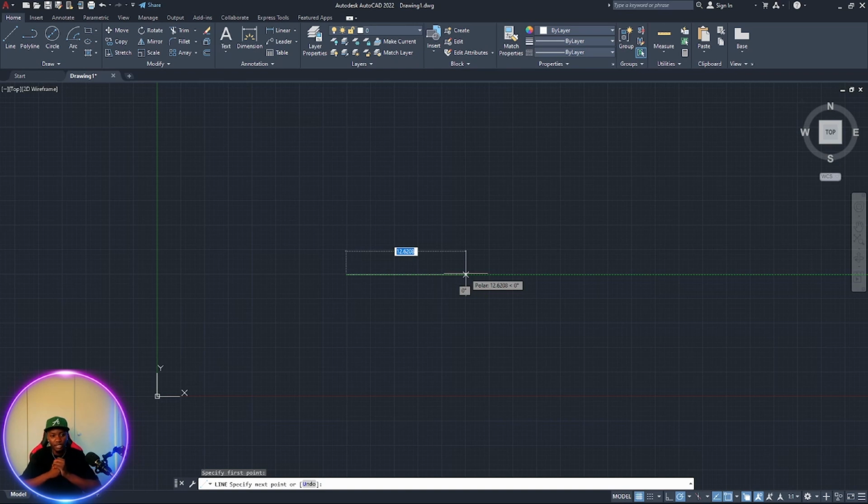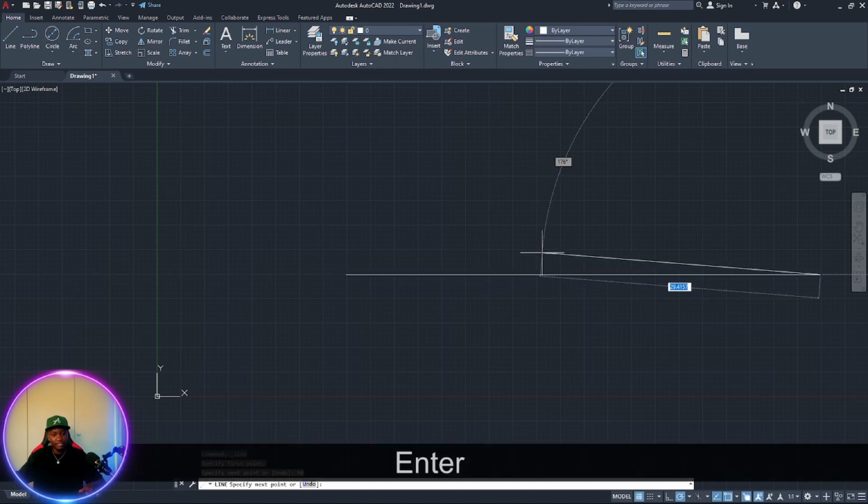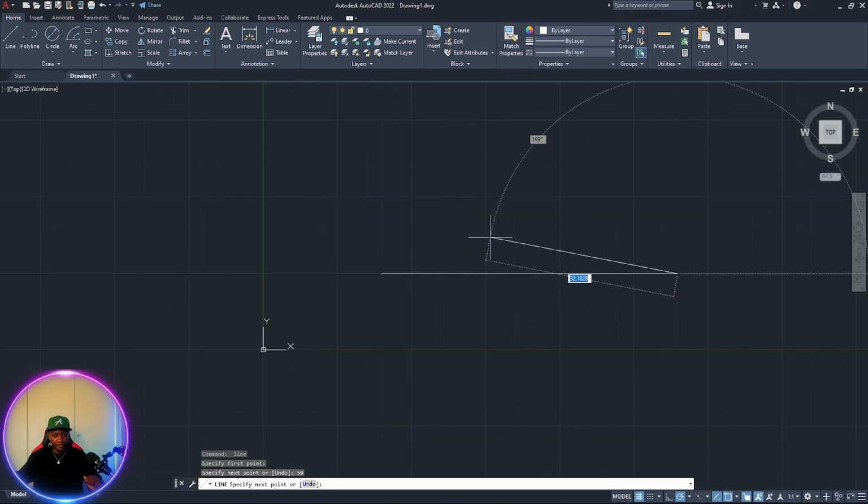So I want the length of this to be 50 millimeters, right? Press enter. There we go. 50 millimeters is on our viewport. Then we go with the width, making sure it's snapping, guys. The green line is important because you know that it's on the perfect degree of your shape. So if the length is 50, let's make the width 30 millimeters.